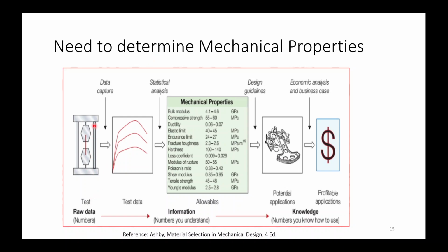This can be done by, as I told earlier, uniaxial tensile testing. Then we get the data, and after analysis we get the properties. Based on these properties, we design our materials, their dimensions, thickness and different sizes. These are all decided using these properties, so that we can make the design economic and reduce the consumption of material.